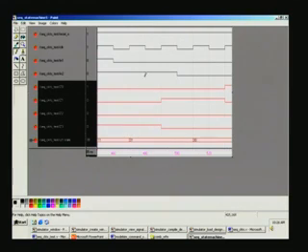In the S1 state, again it continues to be the same, and therefore it remains in the same state. Once again at this point of time there is a change in the IO inputs. So, it is here 00. If it is 00, it should naturally take you to the 00 state, and in this earlier case it was 11 here. So, the Z3 output is set here, and it will change state for this state only at the following positive edge. That is why this is always delayed by a clock pulse, right.